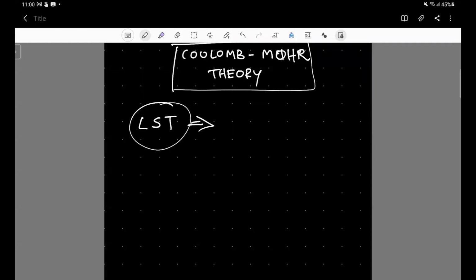I will also be uploading supporting materials for this lecture, because I did not write down all the large matrices, which would consume even more time. So refer to these materials. As you can see, this is nothing new, a very simple process. We have used the same steps to generate the stiffness matrix for a constant strain triangular element.